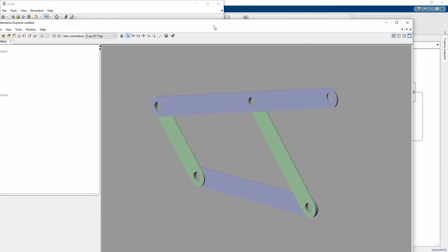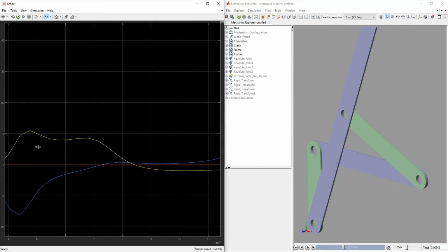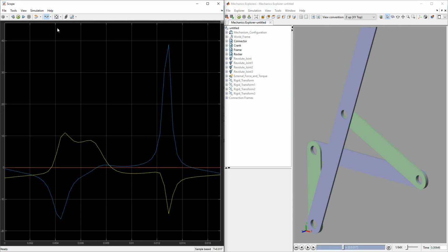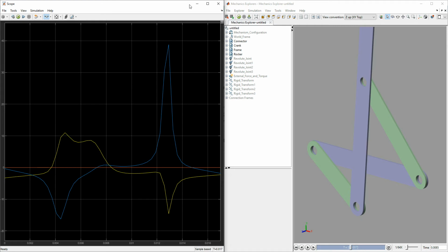Right, so if I come back to this, check this out. So it's suggesting, whoops, around here is some of the highest loads. So that curve, we end up with a spike here. This spike is about 38 Newton meters. 38 Newton meters! Well, Newton millimeters it should be really, because that's particularly what their values have been working to. Interesting, very interesting. What we're going to do is then progress it.